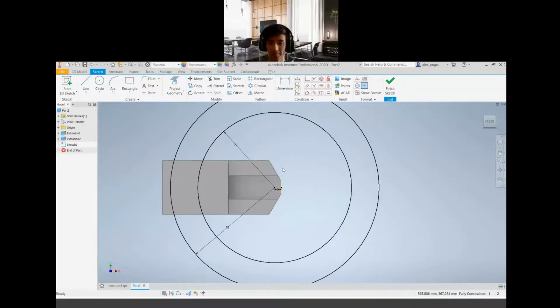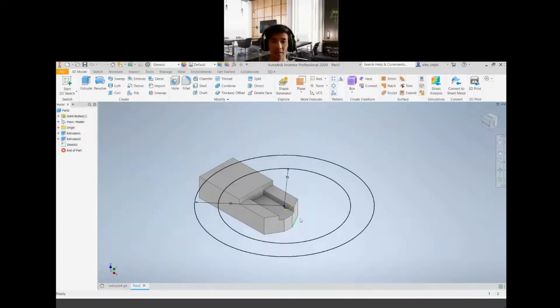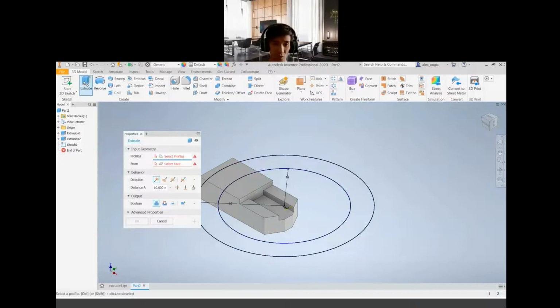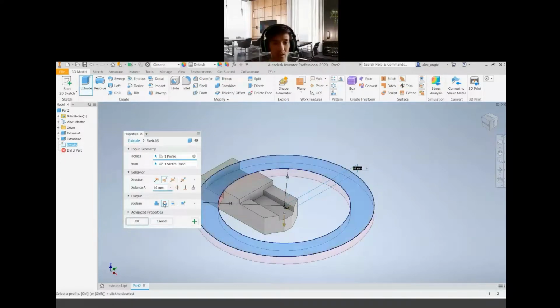Other than that, I assume no problem. So we just finished sketch. Once the center point is already defined there, what we intend to do will be extrude also. No need for us to do any trimming here. So just go to extrude. Okay. So profile, please select here. You see the default is still join. Now we turn into cut. Cut. Okay. Profile. Just select.